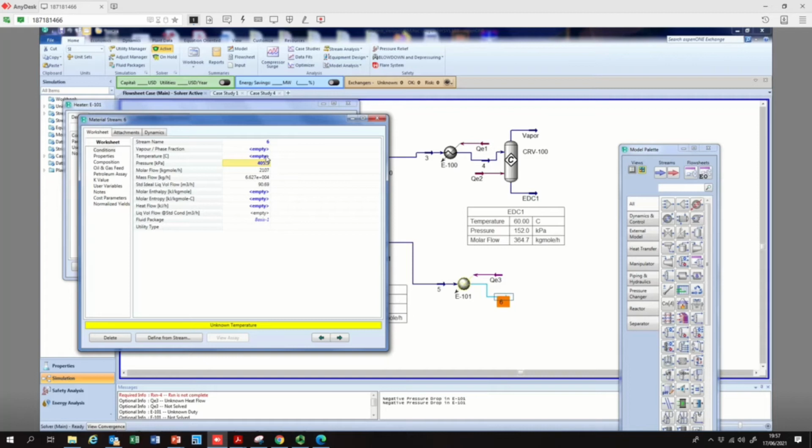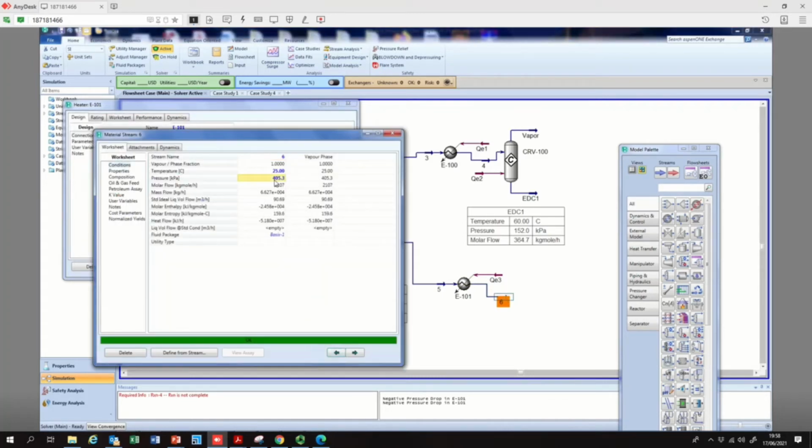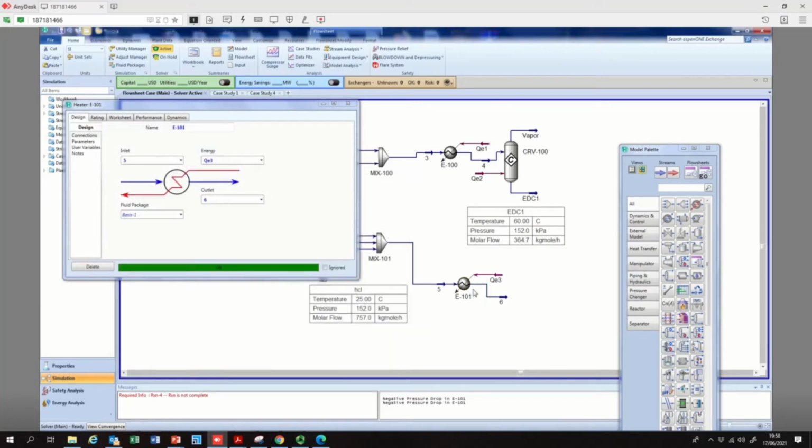And temperature, let's put the same temperature. What's that? 25C. Enter. Oh sorry, I don't know what I did. I made a mistake. So delete it. Sorry. Let's put the temperature to 225 degrees centigrade and pressure to 1.5. And then we will add a compressor now. So the pressure is the same: streams 5 and 6 have the same pressure, but we raised the.